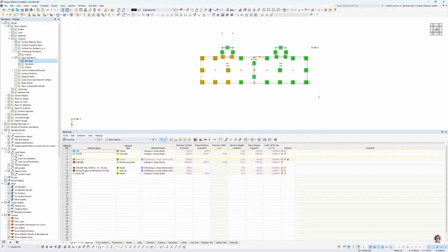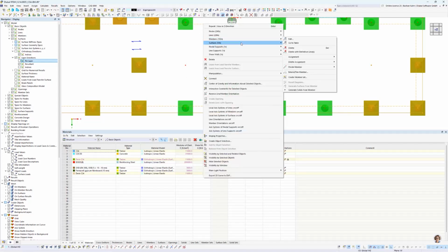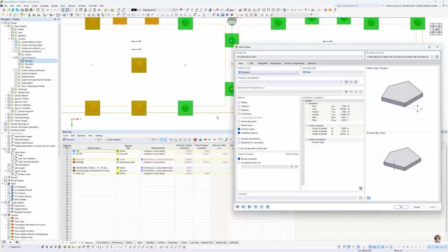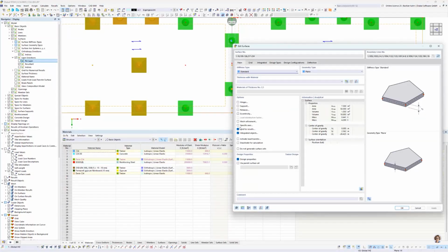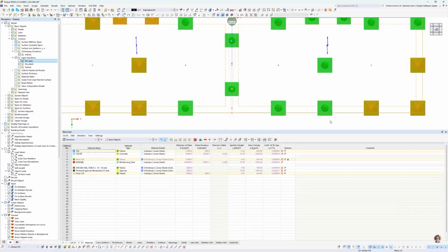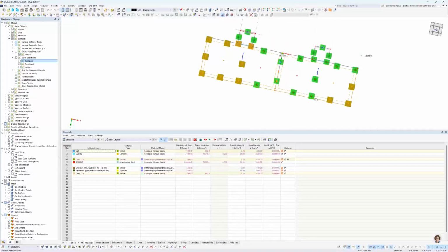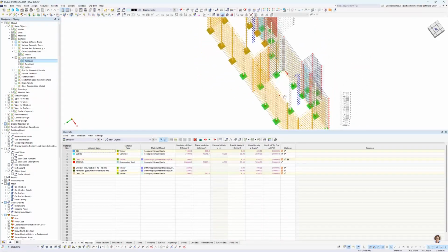Therefore, activate those surfaces, these ones, similar to these, and right click and surfaces, edit. And I have here a specific axis that I can orient. So that's rotated by 90 degrees. And I hope now the stiffness orientation is changing. That is changing. So that's perfect.